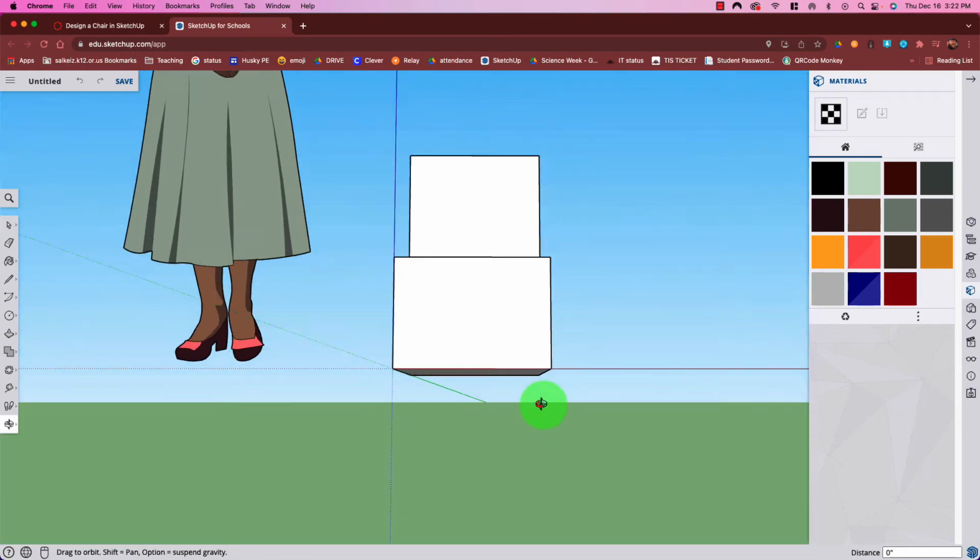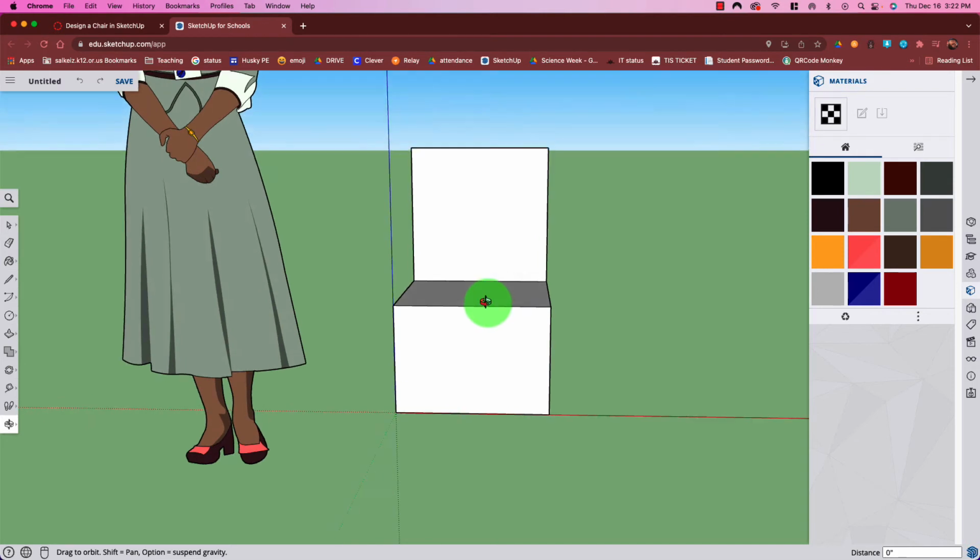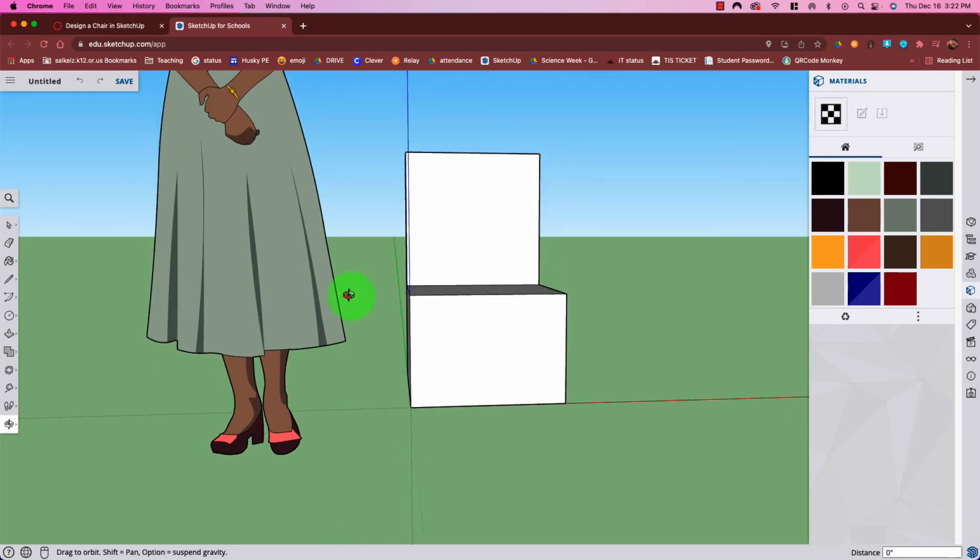The way I'm going to choose to create these legs for this project is I'm going to grab the rectangle tool with R again. I'm going to draw a rectangle on the front of the chair, to represent the space between the legs. So I'll click P to push-pull, but this time I'm going to push all the way back till it says on face or offset limit. And then when I let go, it actually pushes all the way through the object.